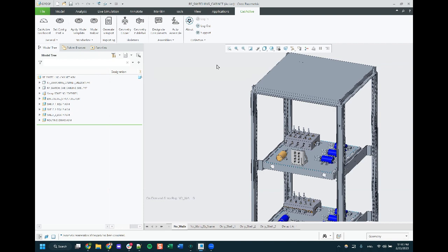This is the way we have it set up right now, to be more like a manual update process using external copy geometries. That's not to say that we can't use this in different ways, right? We could set this up for your company to use assembly context with automatic update. We could set up a listener that updates the location of everything that's been moved when you regenerate, or when you save, or when you check in. There are all sorts of different opportunities here. Just because it's the way it is right now doesn't mean it's the way it has to be. It's not stagnant. We're pretty flexible.